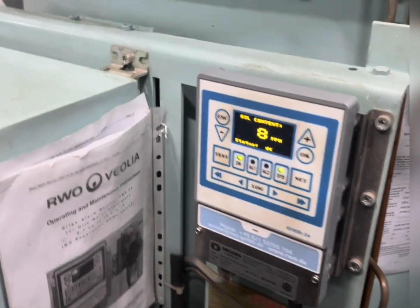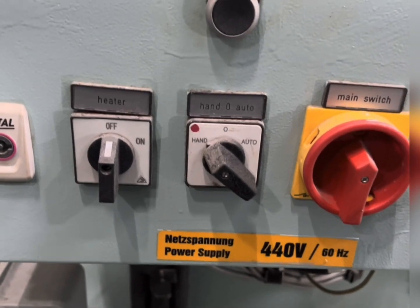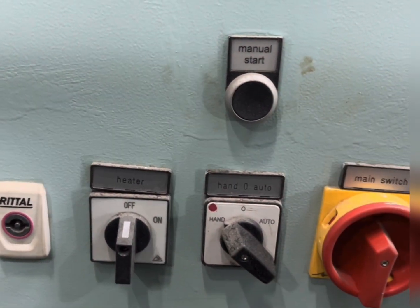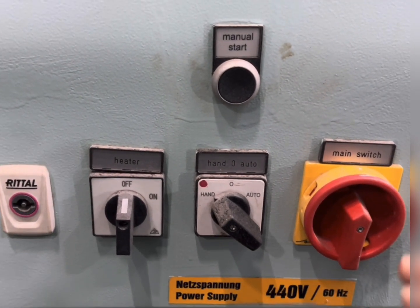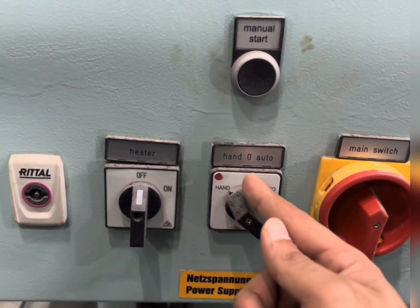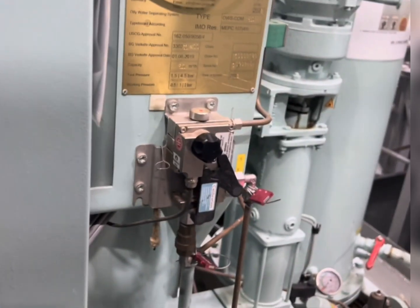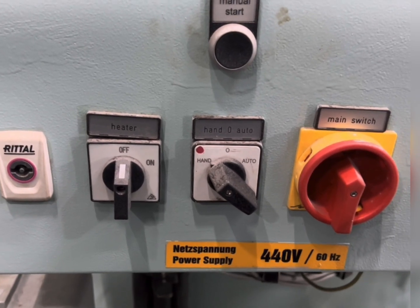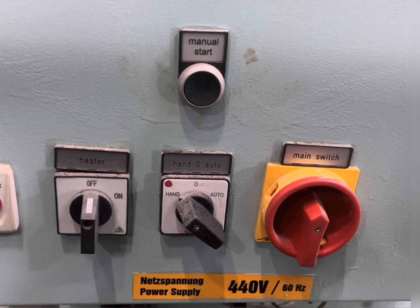So the ppm is around 8 ppm. After preparing the line, how will you start? Put it on the manual mode and manually start. So it will be started, and after finishing pumping to the required level of the bilge holding tank, what will we do? We will manually stop. We will bring it to the zero position and it will stop the bilge pump and the system will be stopped. So this entry has to be recorded in the code D, that is non-automatic operation of OWS.